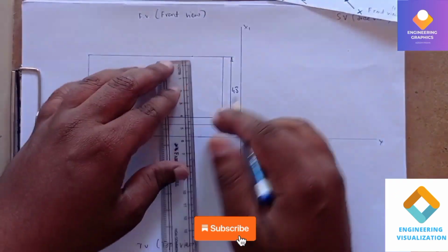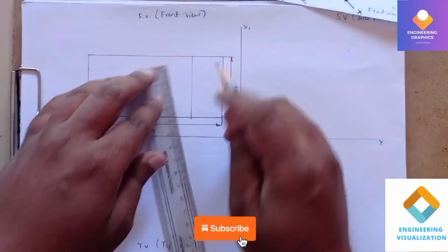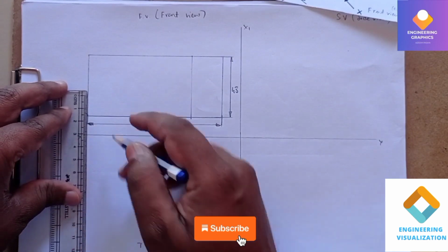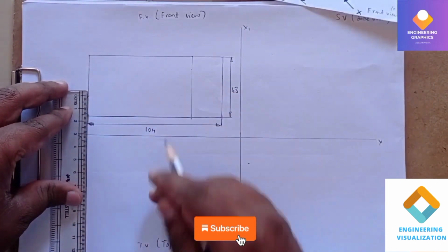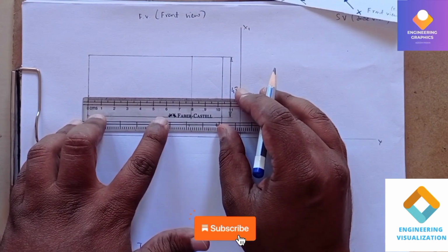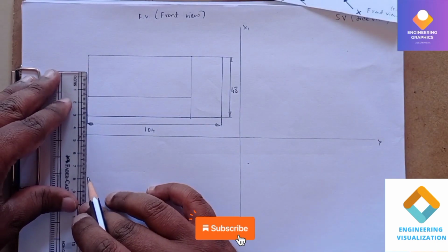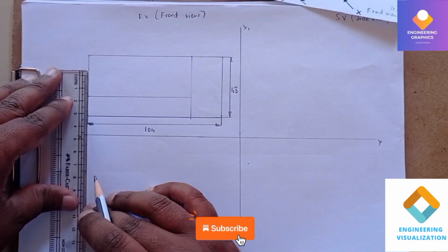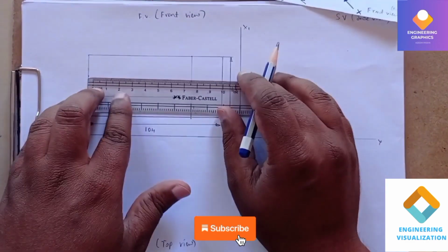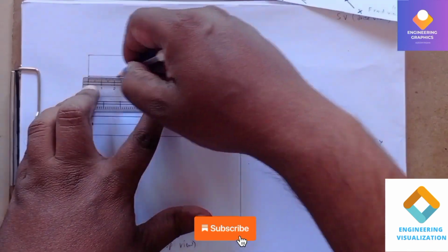Okay, then vertically just draw a straight line. Okay, and then here from this end we should exactly cut it at a height of 16. Okay, so here also I will draw one line horizontally. Okay, and then we need to extend by 16 mm as it is mentioned. It's like steps. Steps were there exactly at 16 mm height. Okay, we can construct that.